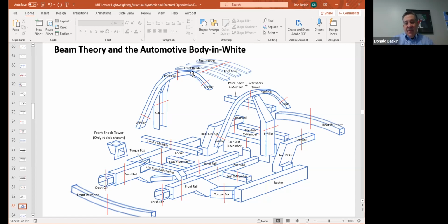But the side impact is all about keeping other cars out of the inside of the car altogether. So you don't actually want a lot of crush space. You want things as rigid, hard and strong as possible, so another car doesn't get inside the passenger compartment in the side impact.